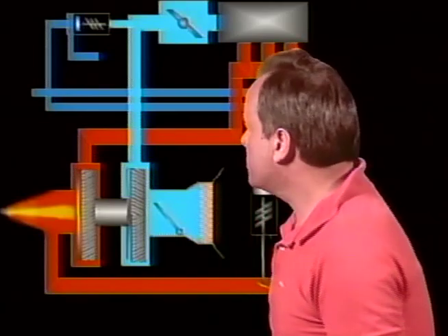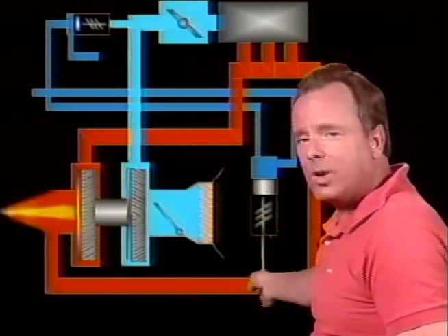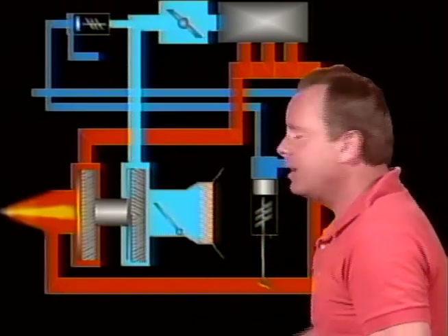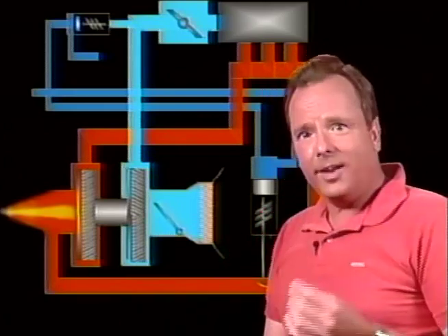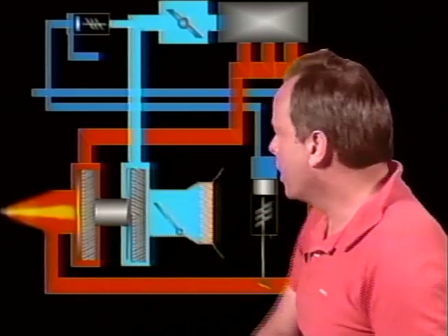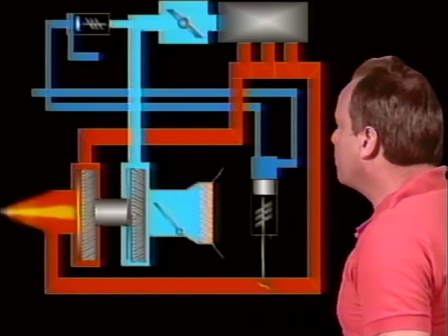And if the engine has 34 inches of manifold pressure or more, it will open the wastegate. That's what a density controller does. It opens the wastegate if you start to overboost the aircraft. All right, the differential pressure controller is an elegant device, and it's what we used to have in a Cessna 340 that had a supercharged, turbocharged system. Let's take a look at the differential pressure controller.